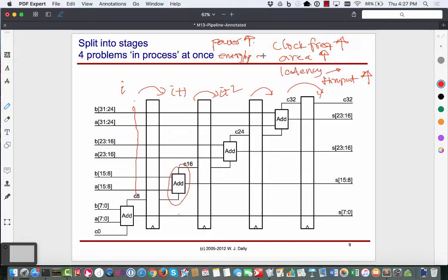So I have two operations going, not specifically the adder example, but imagine that I have a pipeline where what I do with the next pair of inputs depends upon what the outcome was for the previous pair of inputs. Do you see a problem in a pipeline situation? You won't necessarily know the whole output of the previous input before the next input comes. Right, and so I cannot start on the next input before the previous input is right.